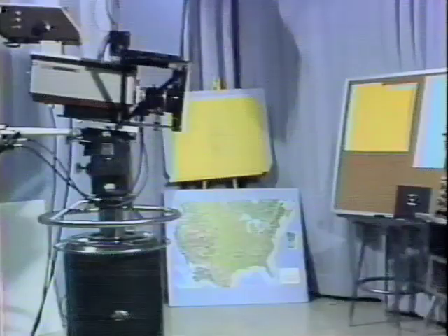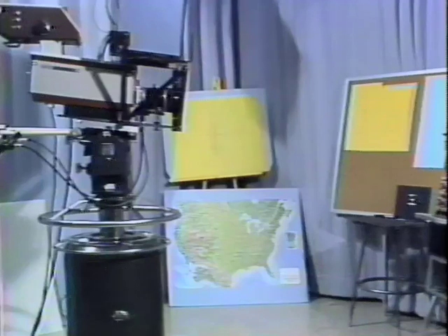The main use for the waveform monitor is to check the level of the video signal. It ensures that the bright sections of the picture do not cause excessive signal voltage, and ensures the dark regions are also at the correct level. This is the scene we are checking, which has a good mixture of light and dark regions. The waveform monitor is used extensively in television studios to check the video signal, and further uses will be described later.